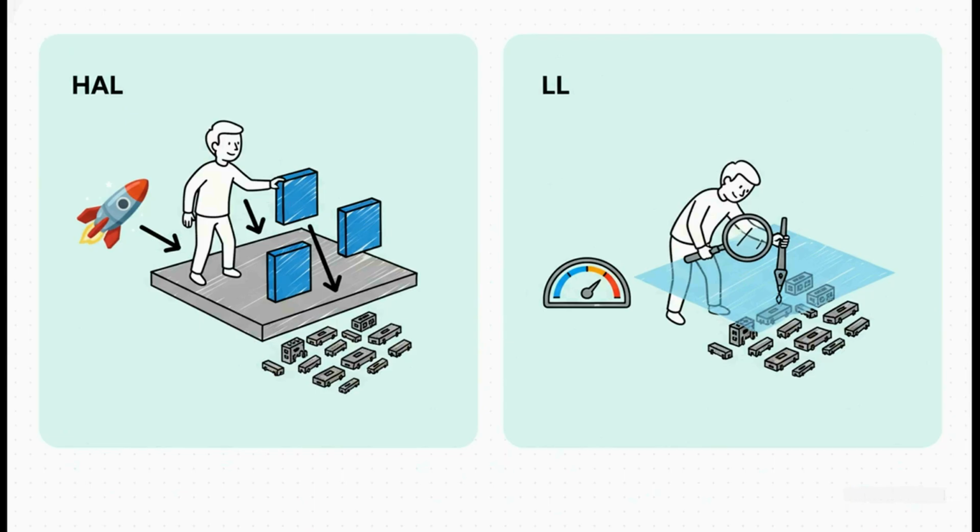The key takeaway here is simple. Start your journey with the HAL. It's the modern way, it's the recommended way. But just keep in the back of your mind that the LL is always there for when you need to squeeze every last drop of performance out of that chip.